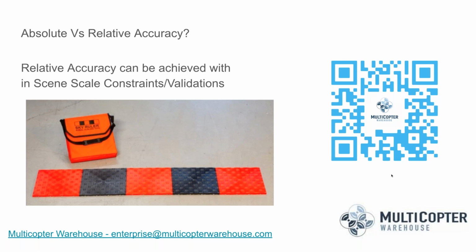You can set what we'll call a scale constraint on one of these, making that 5 feet, and then that scale constraint will apply to all the elements within the project. You can then test or measure the second one of these that you have down in your scene at a slightly different location and validate that you're still getting that 5 foot measurement, and that way you can prove that your model is coming in with good relative accuracy, even though you may not have super high precision global accuracy.